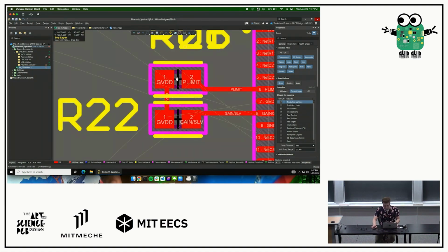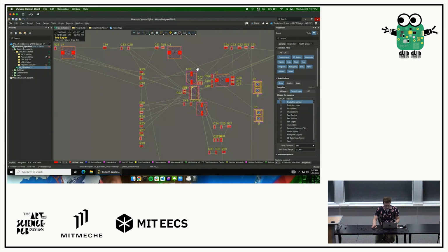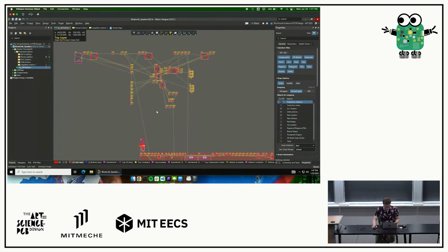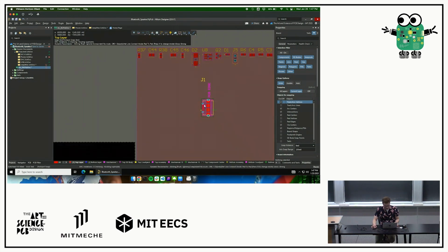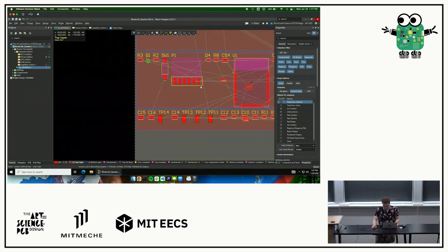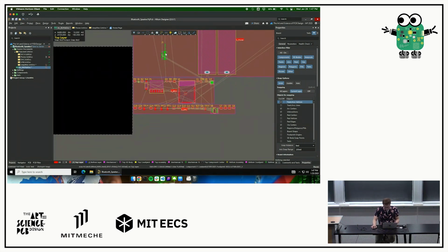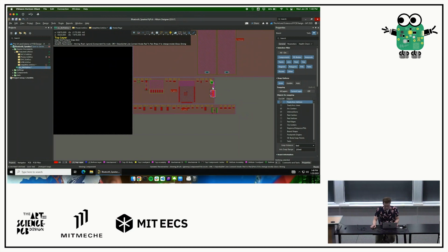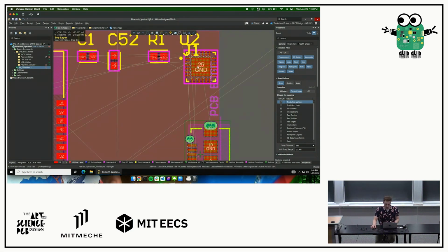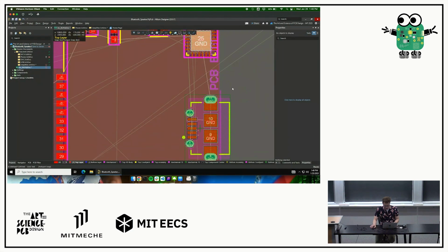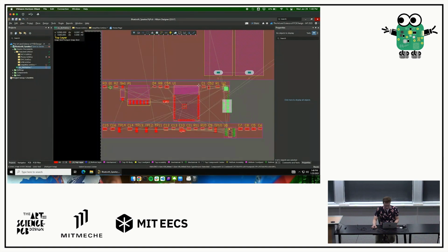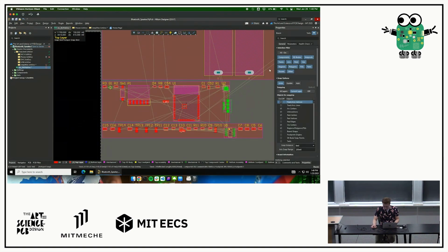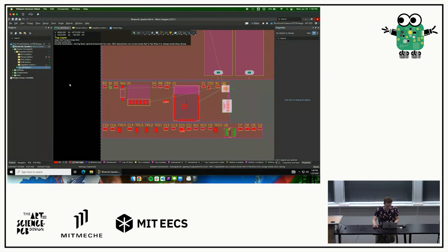Yes. Let's go ahead and see if we can find a differential pair. So if I did this one correctly, let's take a look at USB because that's got some differential pairs. And the USB connector I'm going to drag over here because it routes to this little converter chip. Let's just take both of these and throw them on the board for the sake of argument. Let's drag those. Oh, it seems to be grabbing something else, so I'm just going to pick components, because these are both components. We'll just drag them over there.